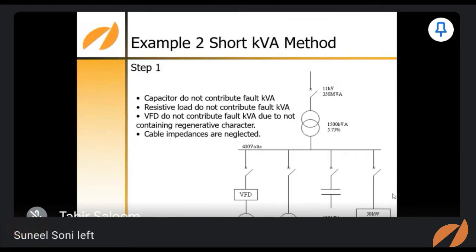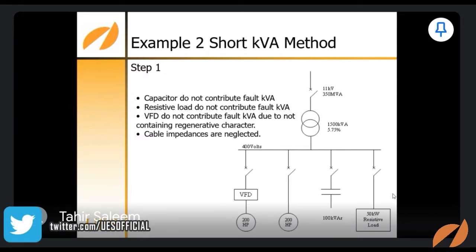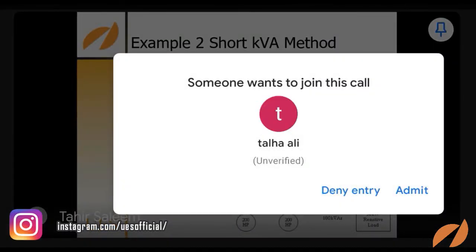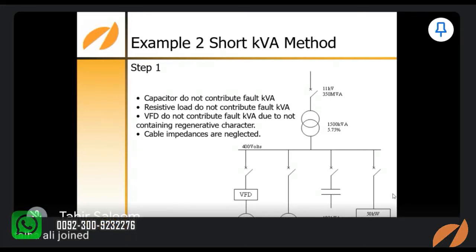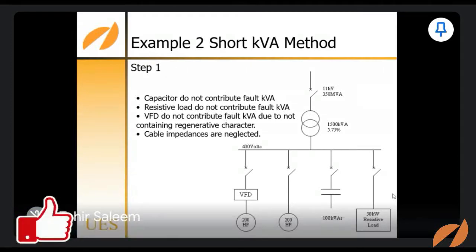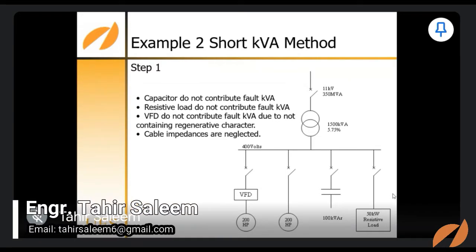This is another practical example, which I told you: capacitors do not contribute fault kVA. Resistive loads do not contribute fault kVA. VFDs do not contribute fault kVA due to not having a regenerative character. Cable impedance is neglected in this case. So you can make a lot of assumptions over there.